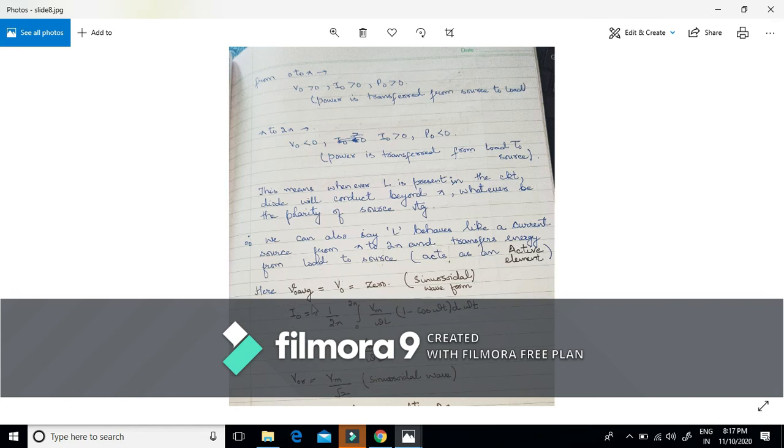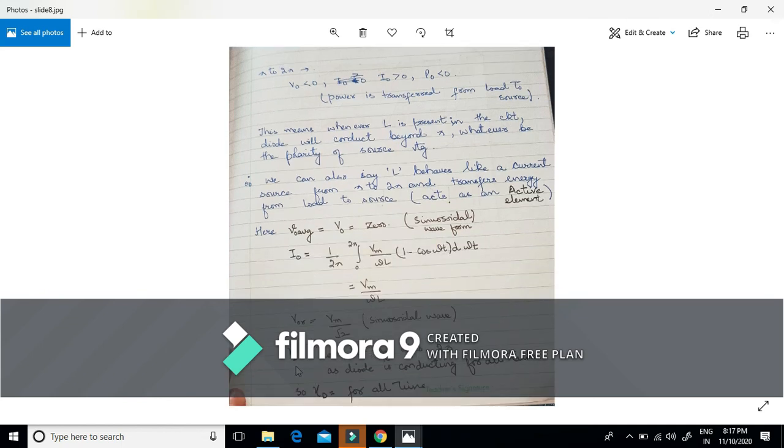Now these parameters: V output average, since this is a sinusoidal waveform, will be equal to 0. I naught will be equal to Vm by omega L. V output RMS, since this is a sinusoidal wave, will be equal to Vm by root 2. Since during the positive cycle and during the negative cycle, during all the cycles, our diode is conducting, we are saying that the conduction period gamma d, we cannot say it's up to 2 pi. We can say gamma d is conducting for all time for this purely inductive case.